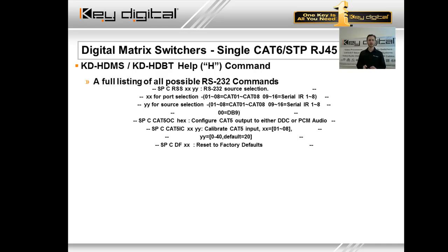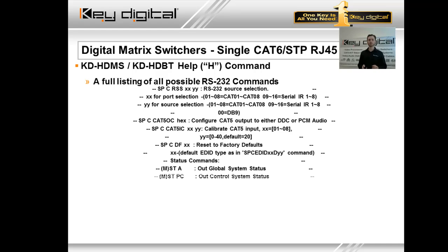Factory default. And with the factory default, you are able to apply an EDID setting that we had seen earlier to the entire system. Okay, versus where the EDID setting that we went through before was 1 by 1 by 1, assuming your different sources may want different handshakes to be relayed to them.